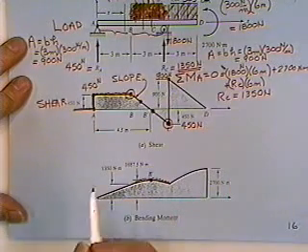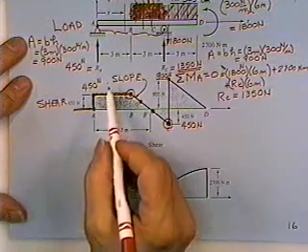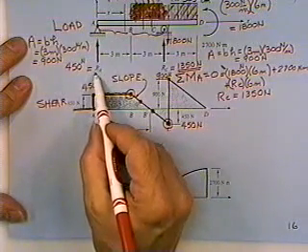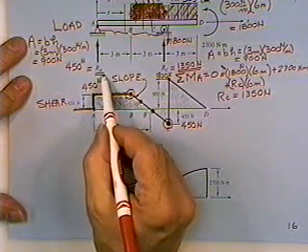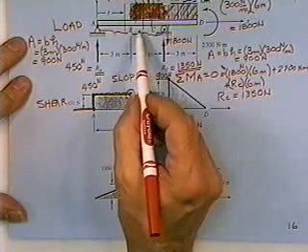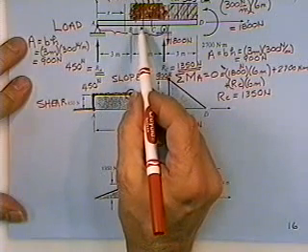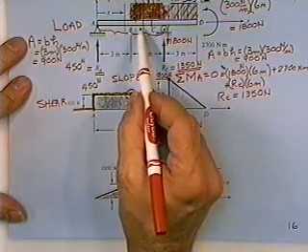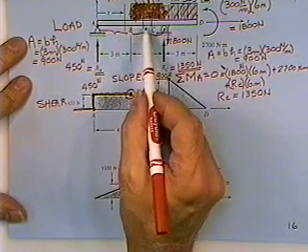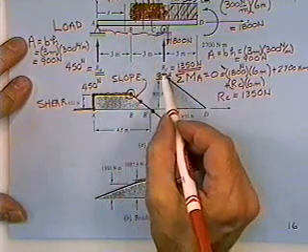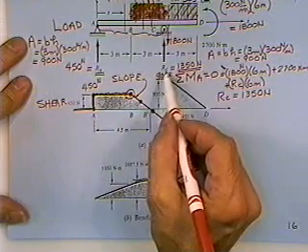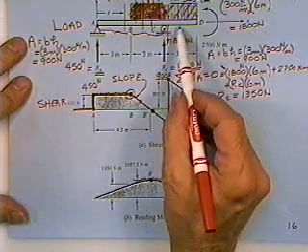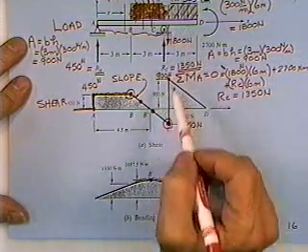Now you can also tell which way to go very nicely. In other words, you'll notice the reaction R sub C tells you he wants that curve to jump up. And you'll notice all these little arrows inside the block. They're little downward pointing arrows, so they want to go down, go down, go down. The R sub C wants you to go up, and the little arrows from C to D say to go down.